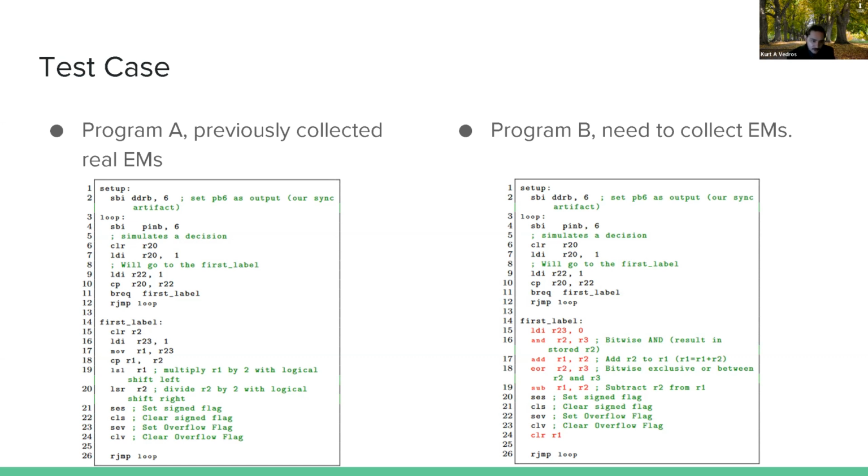The target platform is expected to run either of these two programs, and as such, both should be considered benign cases. Assuming we have already captured the original version of the program, the task is to synthetically generate the electromagnetic signals for the modified version using the assembly code, avoiding the need to engage in a data gathering process from scratch, while being able to detect anomalies considered outside the norm of both possibly executed benign programs.